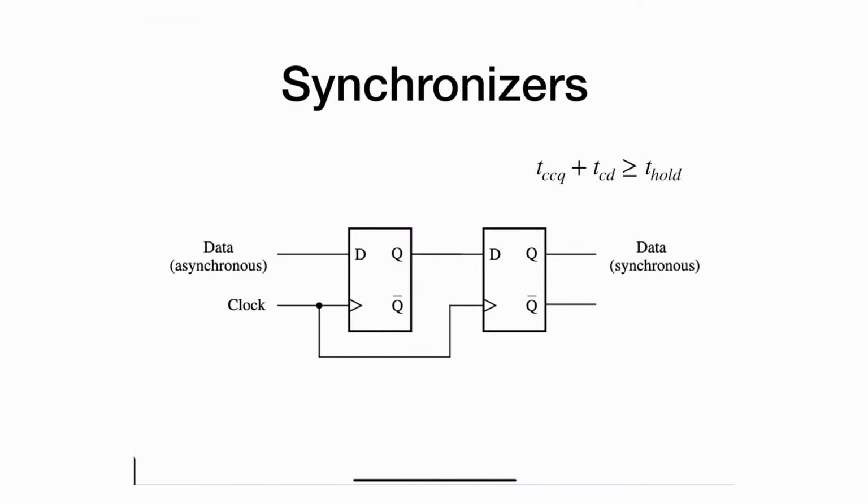And more importantly, we have seen shift registers, or even the synchronizer, which is based on a shift register, utilizes this particular structure, which starts with a flip-flop and ends with a flip-flop. And of course, there's combinational logic. What type of combinational logic? It's actually just a wire. There's no logic whatsoever. So technically, we have something that doesn't have any contamination delay. So unless the T-hold is much smaller, or at least smaller than the contamination clock to Q, you will never be able to cascade flip-flops this way.